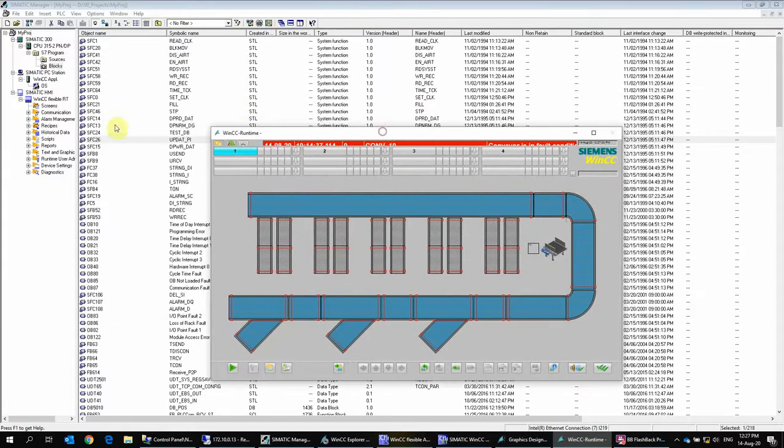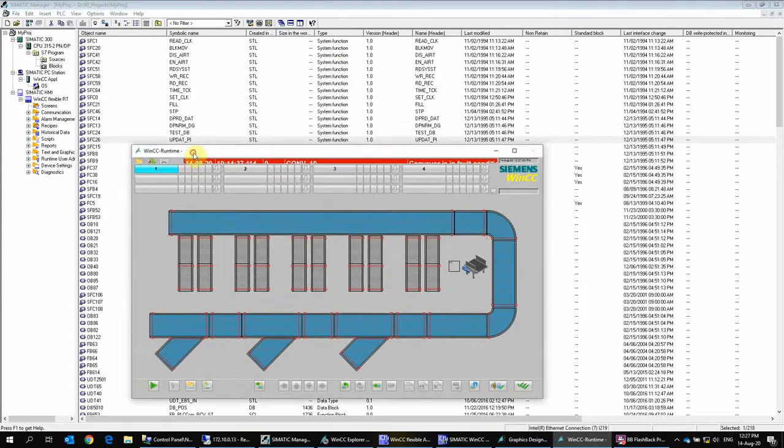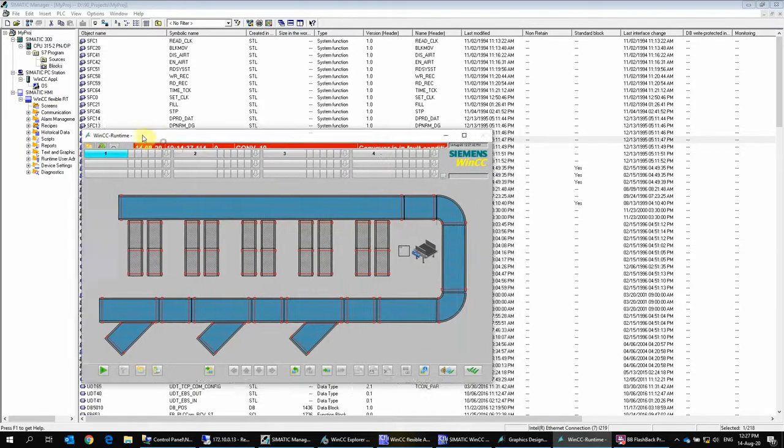the PLC program. Actually, I created the program using the concept of the integrated project. If you can see here, I have the PLC program here. It's the CPU 315-2 PN/DP, and I also have the SIMATIC PC station, or we can say the WinCC project here, and also a touch panel project. You can use whatever you want. In this case, I just use the WinCC flexible runtime. You can run it on my PC itself.